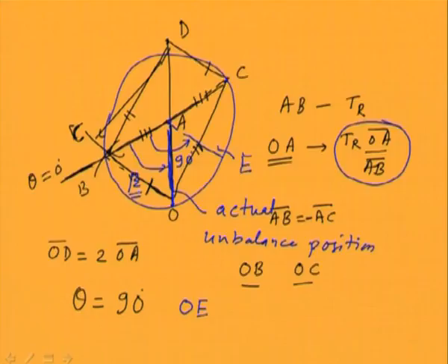Now once we obtain the position and magnitude of the unbalance, that corresponds to plane 2, because we fixed the fulcrum at 1. Now the same procedure can be repeated by fulcruming at F2, and whatever correction mass magnitude and angle we get will correspond to plane 1. So we have to repeat this 2 times.